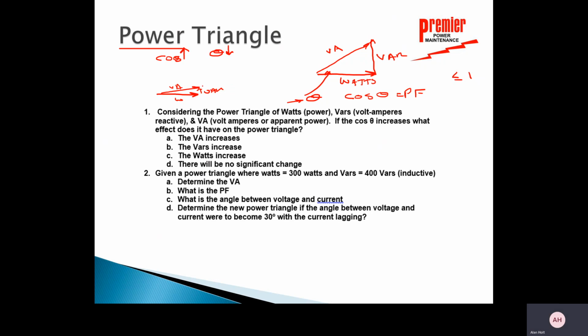So basically the voltamperes stayed the same. Basically the current stayed the same. So if the voltamperes and the voltage stay the same and the angle decreases, then in fact the watts will increase. But in my real world, when the watts are there, that's how much work you're doing, and it doesn't change regardless of what the angle is. That's just what you can do.